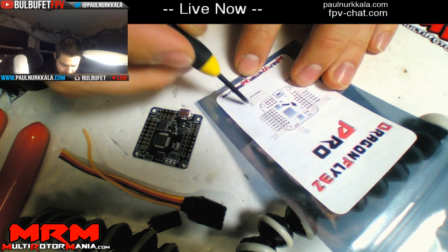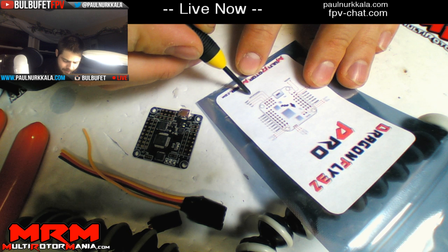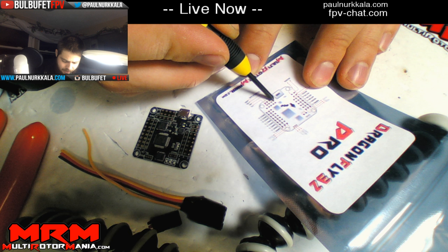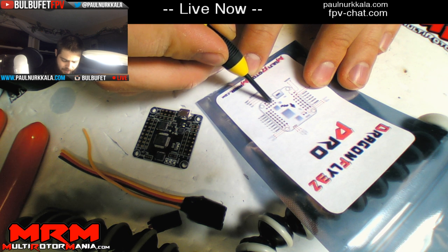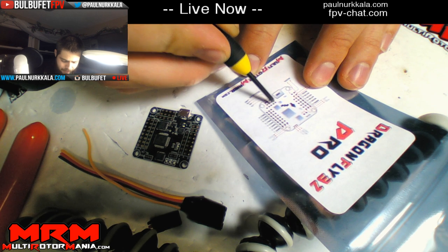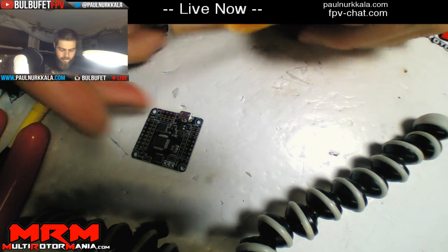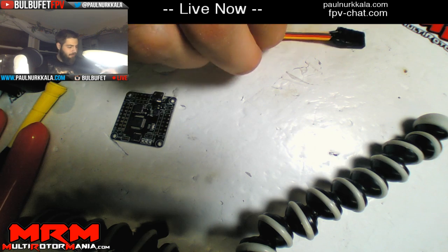You can see that this says OSD/Bluetooth right there, and then right here is the ground, 5-volt, TX and RX. So we need to hook up to that row. This side is the ground. This is the positive, RX, TX, and so we're going to prepare this wire a little bit. Actually, I want to make sure that we've got the proper lengths here.